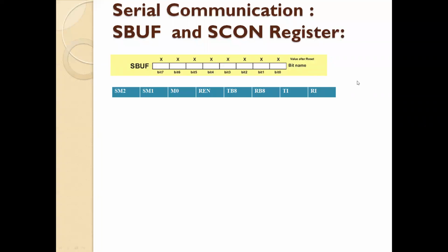Okay, welcome everyone. In this video, I want to explain how 8051 communicates using serial communication, UART. 8051 is an 8-bit processor where 8 bits are processed at a time. While communicating with external devices or processors, it needs to send or receive data. We already know that each memory location has 8 bits, so these 8 bits are to be transmitted.